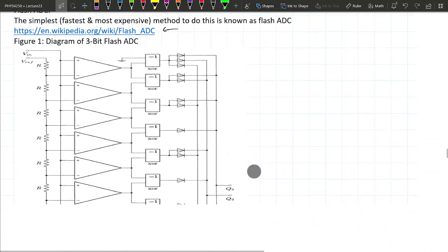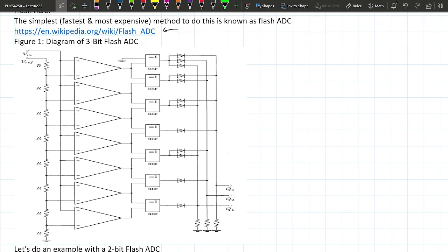And the word flash kind of indicates it's fast, right? So this is a schematic diagram for a flash ADC to do 3 bits conversion. So this can go from 0 to 7, and that's it. What's happening here is that you have a series of comparators: 1, 2, 3, 4, 5, 6, surprise, 7. Or not a surprise, 7. Hopefully everyone knows why it's 7?